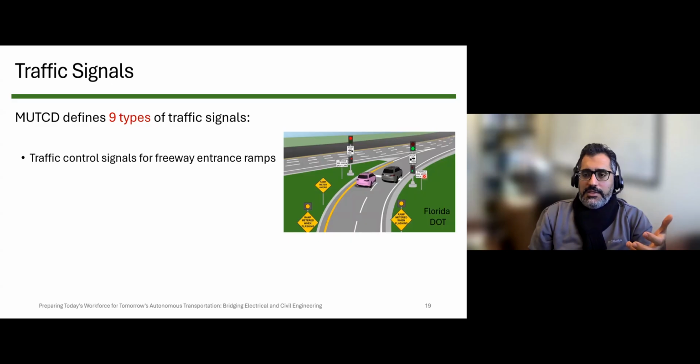You probably have seen them a lot as you are driving and trying to get onto freeways or highways. Why do we do that? It is because we give the highest priority to the movement of vehicles, mobility, here on the main corridor. So we try to control accessibility on those freeways and highways, meaning that if all of a sudden a huge demand goes from on-ramps into the freeway, it could disrupt the flow on the main corridor. But what we do is make this entrance gradual, so we avoid a disruption of traffic on that major corridor. For that, we usually have these ramp meterings.